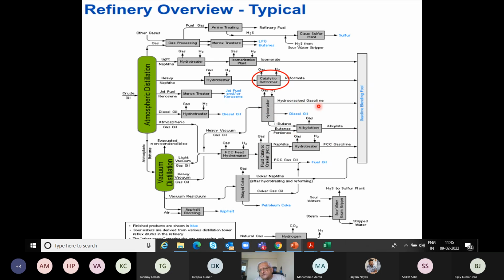And in fact, there's a stream coming from the hydrocracker. In other words, any heavy naphtha stream, or even something like boiling above 95 degrees. Any naphtha stream which can be actually blended into the gasoline pool is a candidate for blending into the gasoline. Okay, provided the gasoline overall actually meets the specifications that are laid down by the government on the gasoline which is sold in the petrol station.